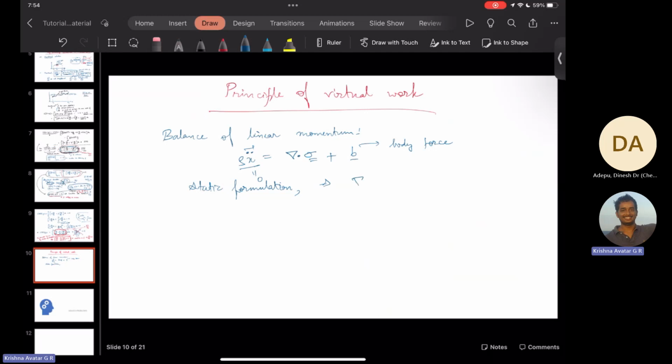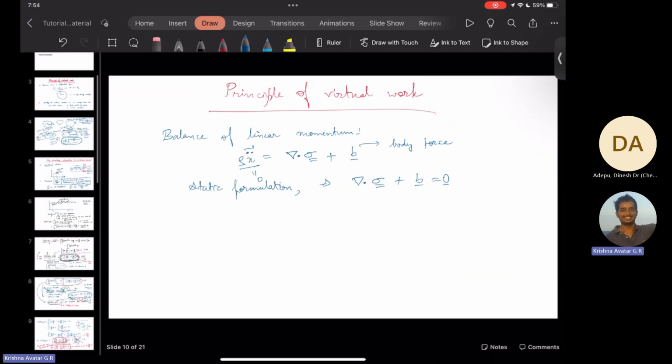So this means that all we are dealing with is the divergence of the stress tensor plus the b vector is equal to the 0 vector. So these kinds of problems deal more with when the body is deformed and we're looking at the stress, in what we call quasi-static loading, right? That it's deforming very slowly, such that the time derivative is almost close to 0, isn't it?